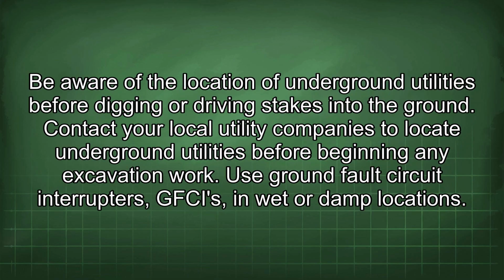Be aware of the location of underground utilities before digging or driving stakes into the ground. Contact your local utility companies to locate underground utilities before beginning any excavation work.